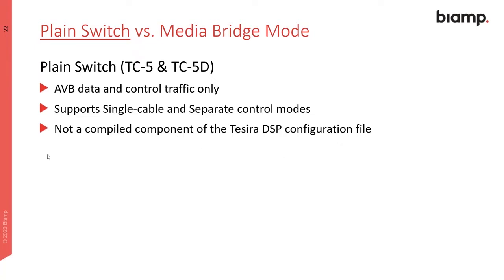So you will not have a block. Anytime you have a Biamp device, usually you will have a block dedicated to that Biamp device. For example, if you have a Tesira Forte, you will drag a Tesira Forte and place it into your software. If you have a server I/O, you will add all the inputs and the outputs of that particular server I/O. In the case of the TesiraCONNECT, you will not have a block. It is a connectivity box to your devices. So there is no block. You will be able to discover it through the software, through the device maintenance, but there is no dedicated block in the device.